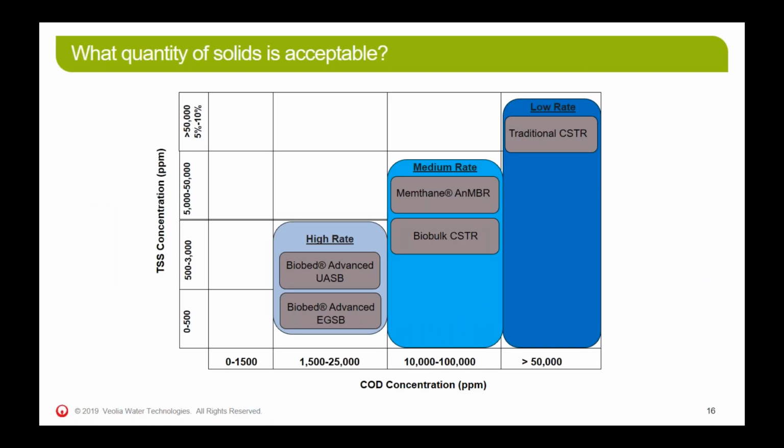And as Jill highlighted, today we will be mostly concentrating on the high rate systems, because the high rate systems are more sensitive to the type of solids that we were describing as compared to the systems that utilize more of a bulk approach to the treatment. So we want as little solids as possible in the effluent, so we want very little solids in the influent to the systems as well.